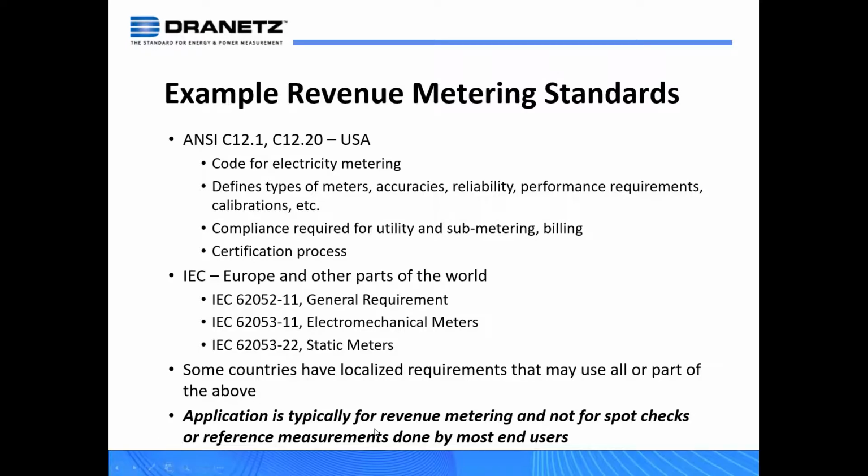But the application is typically for revenue metering, but not for spot checks or reference measurements. So typically when money is associated, you're going to bill someone or you are going to be billed. Well, then these kind of come into play. When it's used for reference, you do not have to have a certified meter. Usually certified meters are much more limited in their capabilities because they're usually fixed installed, and they're built and cost effective just for that voltage, just for that current, and specifically that wiring configuration where it's going to be installed.